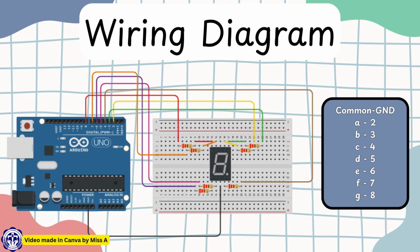Next, connect each segment of the display to its corresponding Arduino digital pin, making sure that each segment passes through a 220 ohm resistor to limit current and protect both the LED segments and the Arduino. Specifically, connect segment A to pin 2, segment B to pin 3, segment C to pin 4, segment D to pin 5, segment E to pin 6, segment F to pin 7, and segment G to pin 8. With these connections in place, each segment of the display can be safely controlled through the Arduino program.